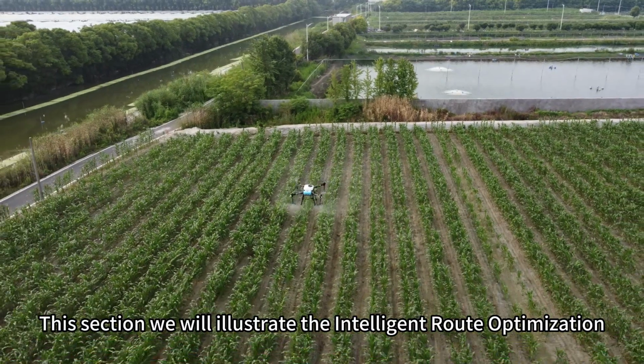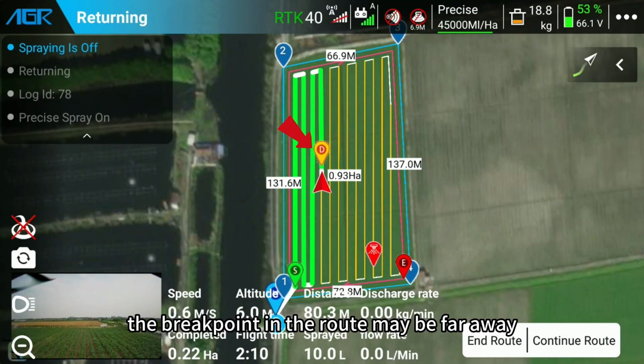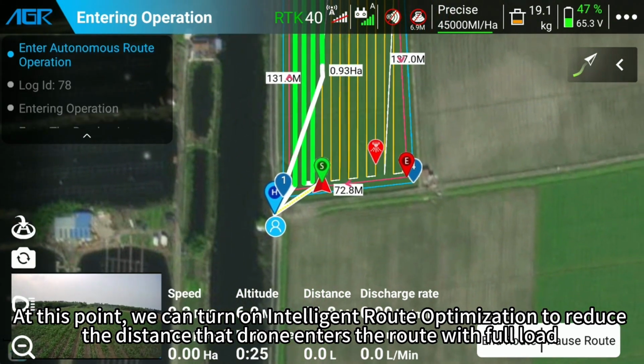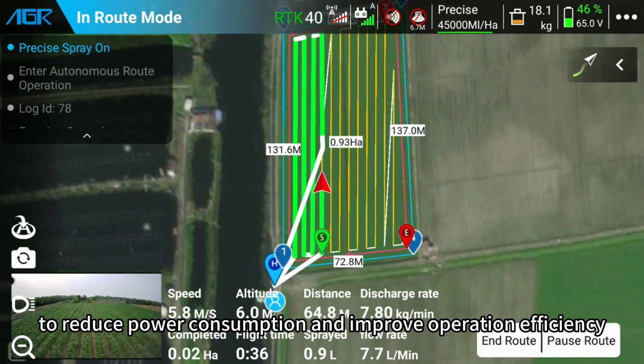This section we will illustrate the intelligent route optimization. During route mode, the breakpoint in the route may be far away. At this point we can turn on intelligent route optimization to reduce the distance that the drone enters the route with full load, to reduce power consumption and improve operation efficiency.